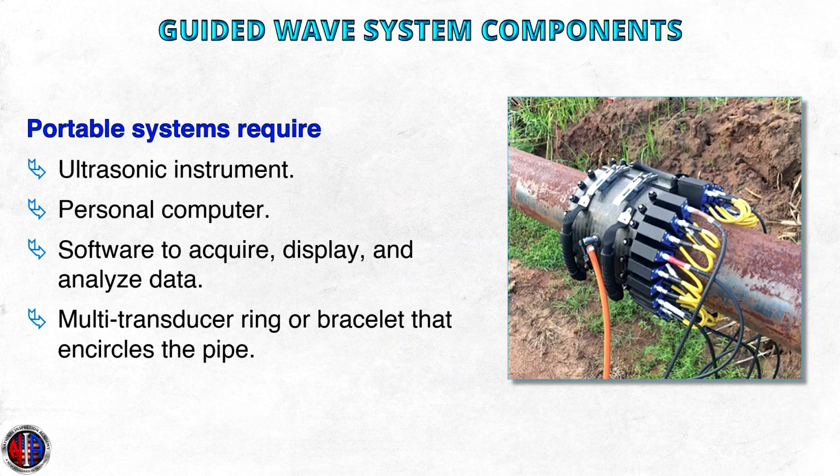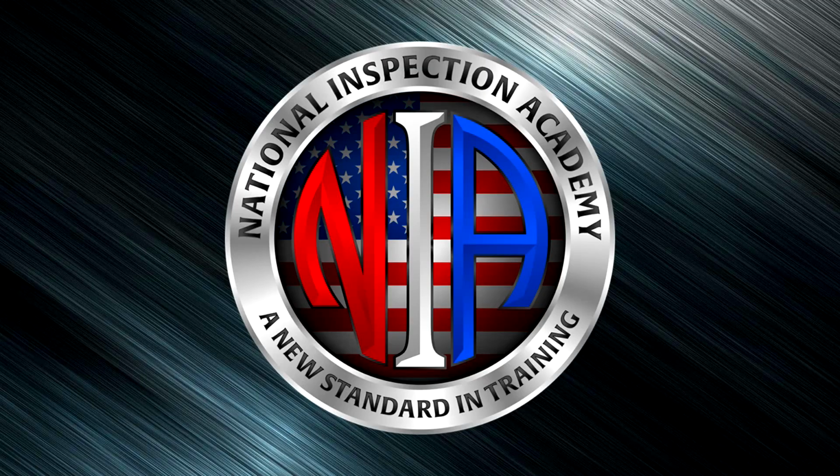Guided wave system components. Portable guided wave systems require an ultrasonic instrument linked to a personal computer to drive the software that acquires, displays, and analyzes data from reflected ultrasonic energy from a multi-transducer ring or bracelet that encircles the pipe. And that completes this lesson.